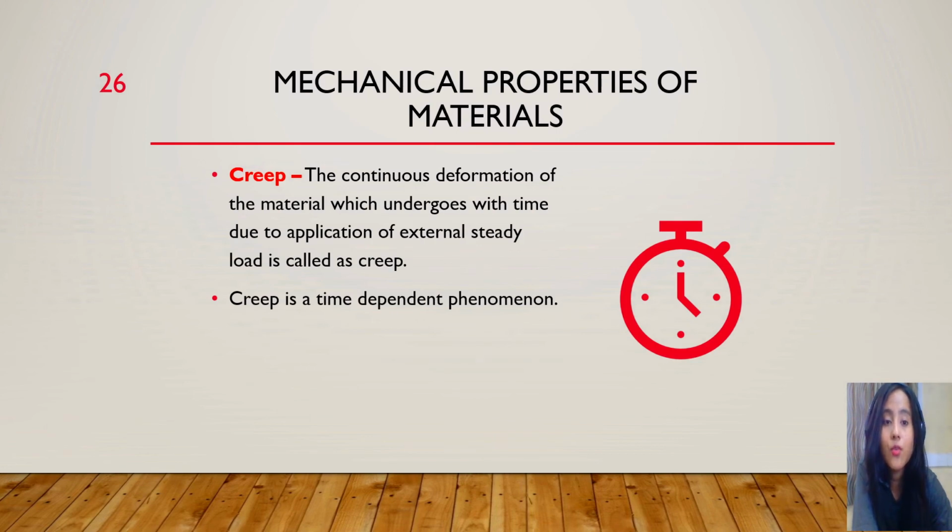So creep is totally a time-dependent mechanical property of a material. The continuous deformation of a material with time under the application of an external steady load is called creep.